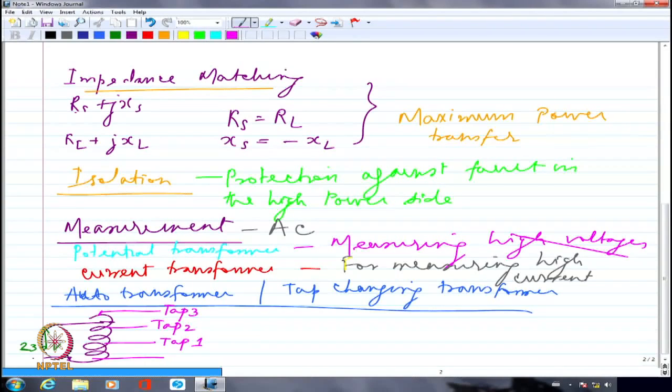So I would say the voltage at the terminal of the generator will be 400 kV minus whatever is my R plus jX of the transformer and generator multiplied by the current. Of course, I have to include the power factor angle, no doubt. This is how I am going to get terminal voltage.